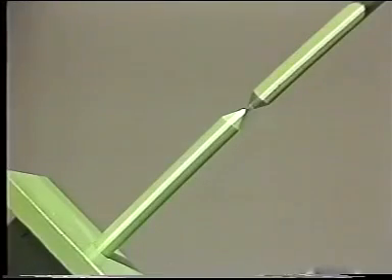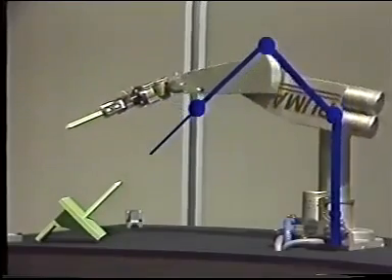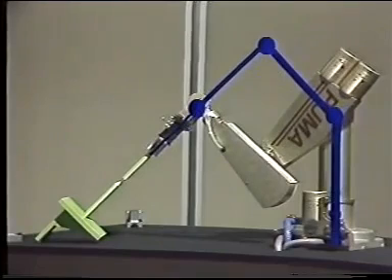And you can see the gripper's gone back to the same position, but the arm, although it looks similar, is in a completely different configuration, as you can see, because you can now read Puma's name. And here's yet another configuration, but with the gripper again having gone back to exactly the same place. So that's 4 different basic configurations of the Puma for a given gripper position and orientation. And in fact, we can get another 4 because for each of those, there's a wrist flip Puma can do, and that would give us 8 configurations in all.